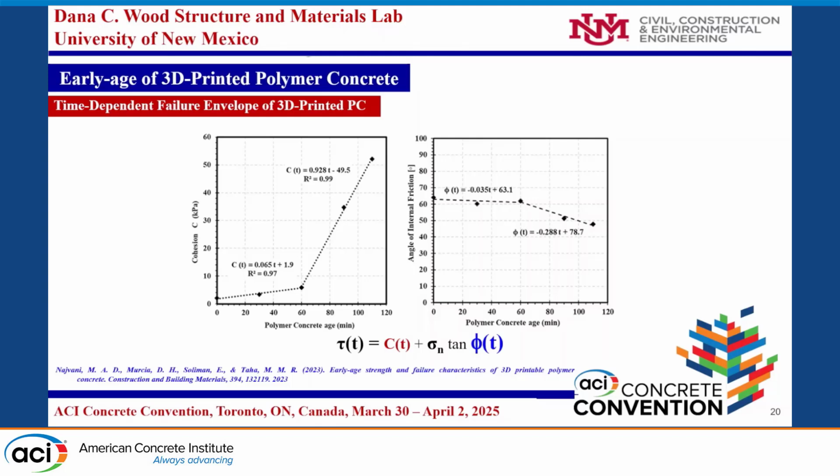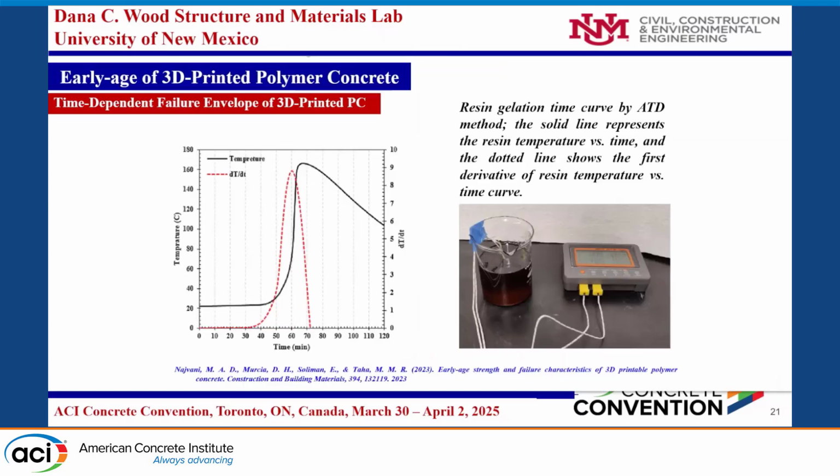this graph into two categories, the first one from 0 to 60, we can call this a printability window, where we can print in that range. And after 60, it's the structural build-up and the shape retention ability. And this confirms why at 60 minutes we are starting to have this significant bilinear effect.